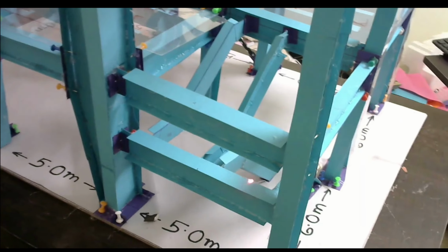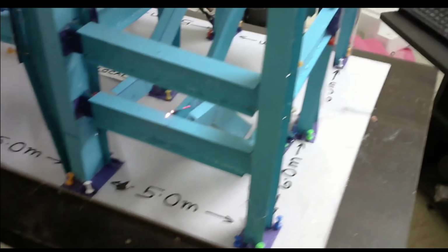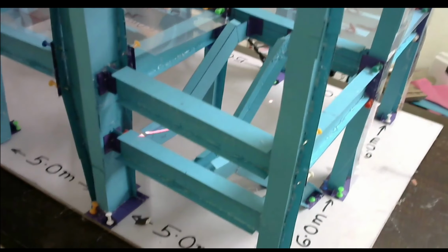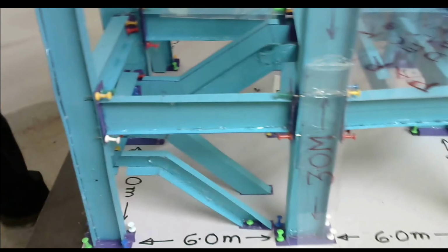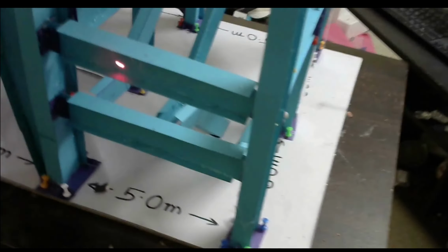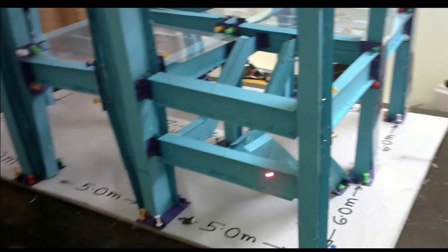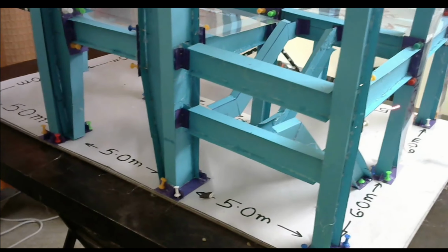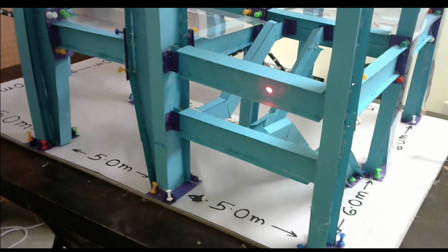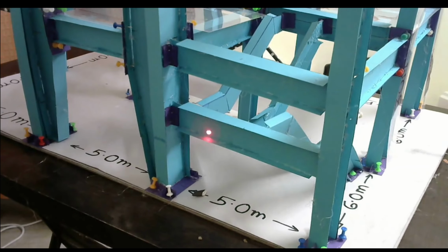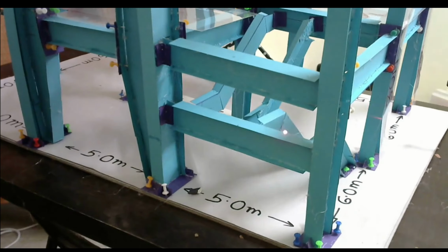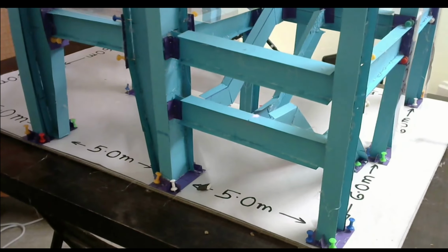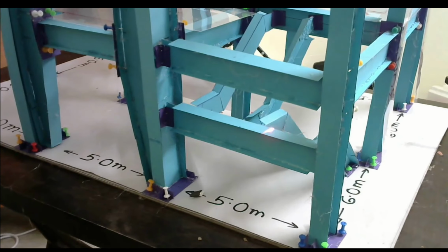The distance between the stringers, say suppose it is 2 meter, so we can leave LX LY as 2 meter, but LZ will be 5 meter. This beam LZ is 5 meter. For this landing beam also LZ is 5 meter. For this beam LX, LY, LZ all are 5 meter. But for this beam LX, LY we need not define it. The maximum LX, LY, if the stringer is spaced at 2 meter, then maximum LX, LY will be 2 meter.